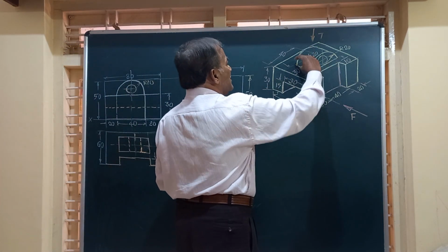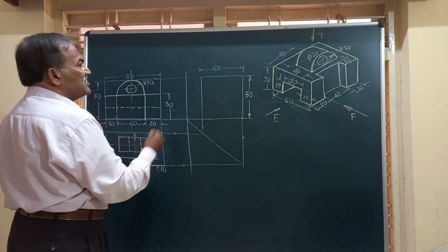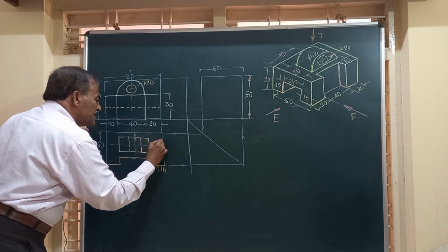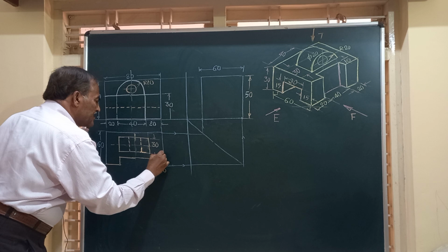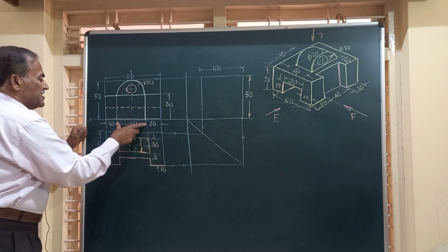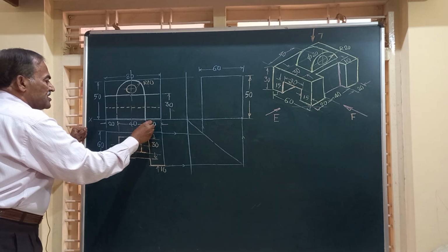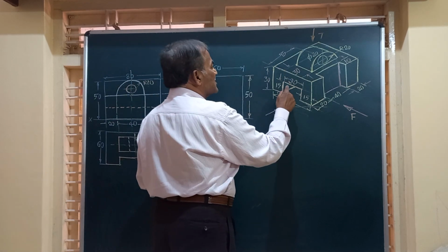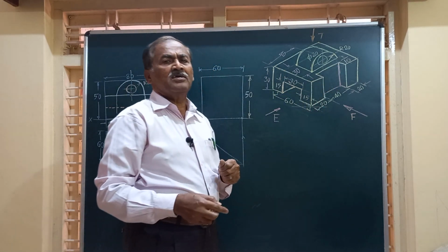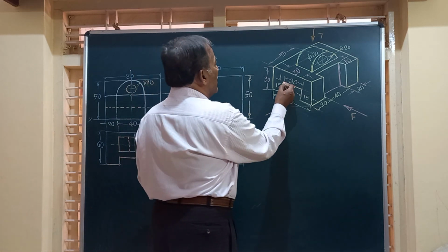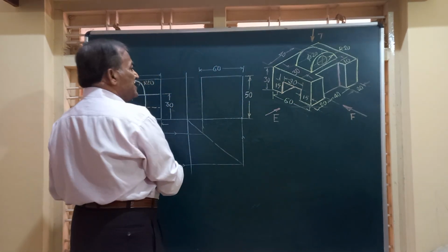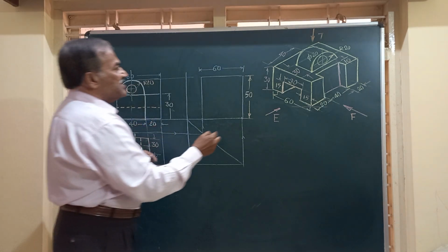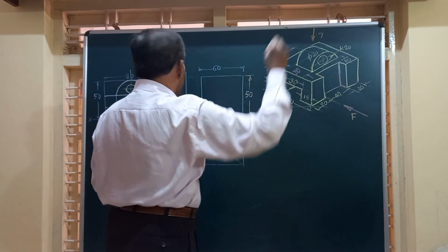So we have the slot drilled, the rectangular face we have got here, which has a dimension of, this is 30. So this dimension is 30 and the other dimension is 40. I have taken exactly from here, so it is 40. Friends, what else do you see in the top? In the top, this slot which is cut throughout the length of the object is not seen. So I have to mark exactly in the center of that. That is, in the top view, we have to mark two lines to represent this. So it is there throughout the length.